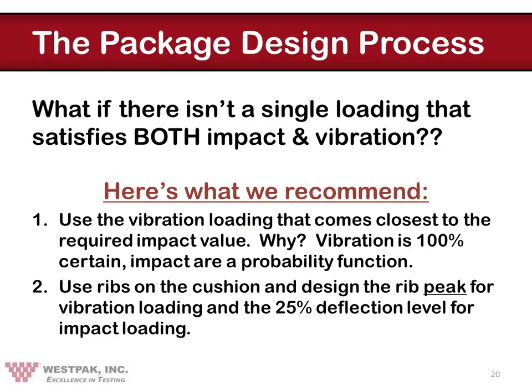And vibration is a necessary function because its probability is 100% during shipment. When we design the ribs and you have the loading necessary at the peak of the rib, you want to design the loading for a 25% deflection of the rib for the impacts.